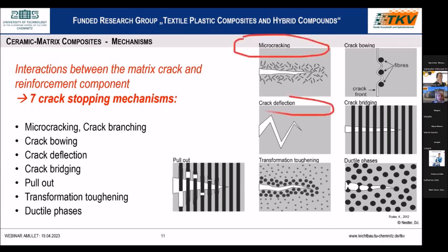Furthermore, one could bridge a crack with one or more particles, similar to joint boards with nails. Furthermore, one could relieve the tensile stresses at the crack tip by superimposing corresponding compressive stresses that must be generated in the microstructure. Most of these fracture energy dissipating strategies can be realized by multi-phase microstructures in which a second ceramic or metallic phase interacts with the crack. This leads to so-called particle or fiber reinforced ceramics.